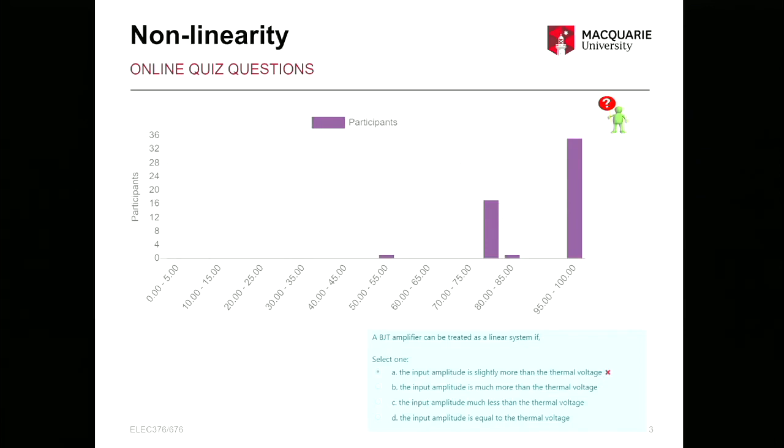Less than the thermal voltage, and really smaller than the VBE on, so the BJT will not work. Yeah, exactly. You're right. That is why we have the DC bias. So keep it on, and on top of that, we apply this voltage, right? If there was no DC bias, then it is not enough to turn the BJT on.